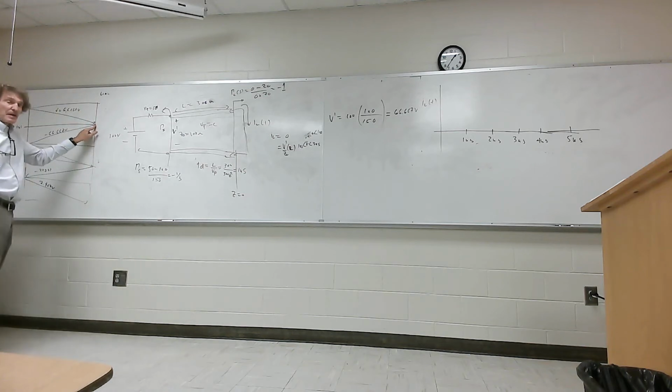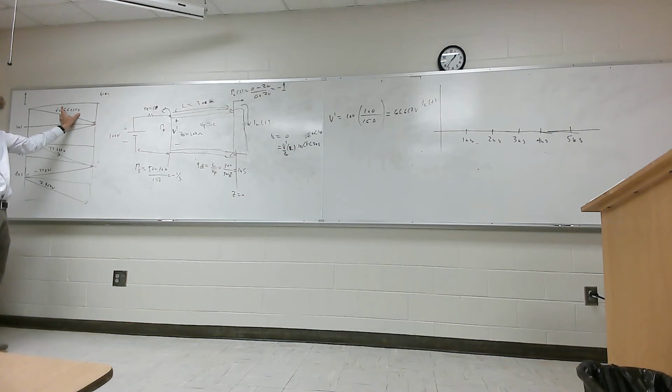You all follow me? Then I take this voltage, divide it by Z naught, and multiply it by 2, because remember, it's V naught over Z naught. That would be the current waveform coming this way. When it hits here, it's that current waveform times 1 minus the reflection coefficient, so 1 minus a minus 1 is 1 plus 1, or 2 times that current waveform.